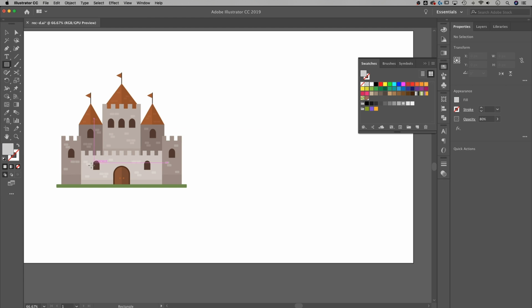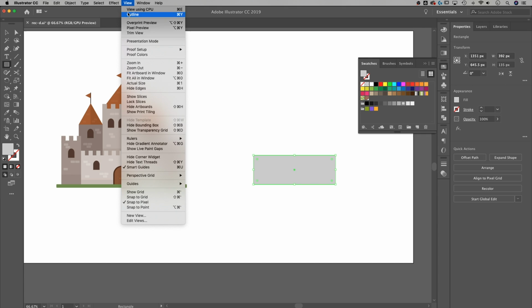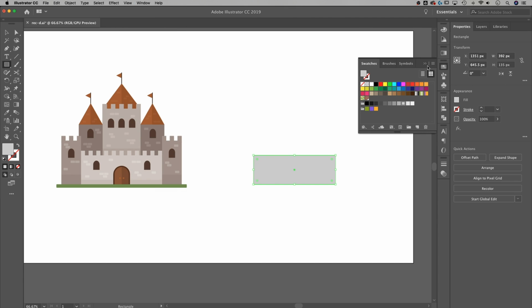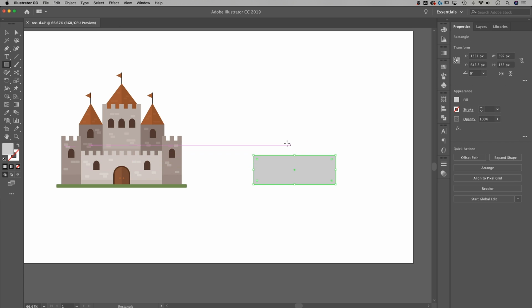So we'll start here for maybe this main piece right there. And I do have these smart guides set up, but you don't necessarily need them. Just kind of make your own size rectangle for the front. Eventually the smart guides will help you line things up. You can go to view down to smart guides to turn those on. And those are gonna be all the pink lines you see lining everything up just like that. Okay, so we got the base wall built.